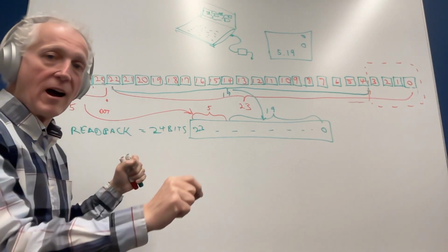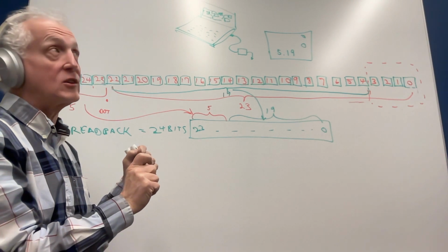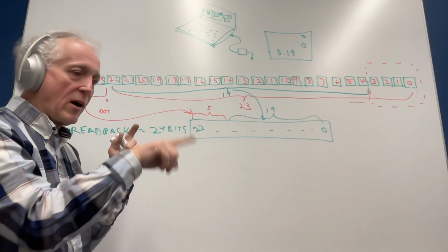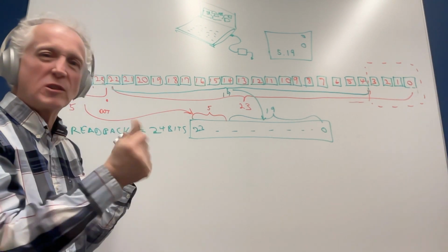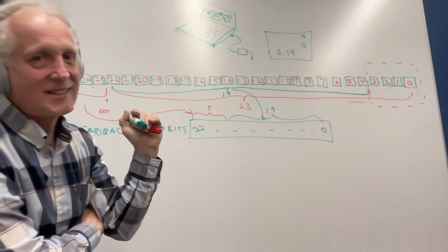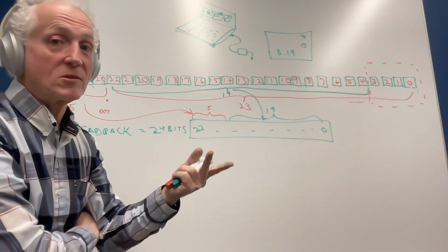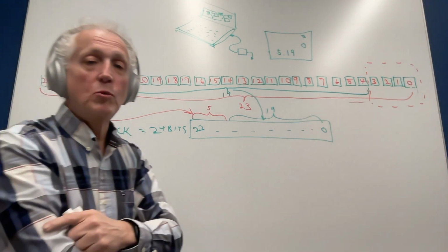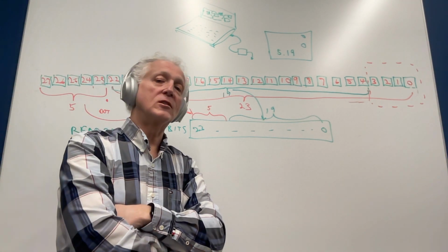That's why that's in the library, arithmetic shift. Easy for me to say. And it's a barrel shifter in the hardware, so it's easy to do, very few instructions. However, it doesn't exist in the 100 core or the 200 cores for that matter. And so we got to do this shift in a smarter way.